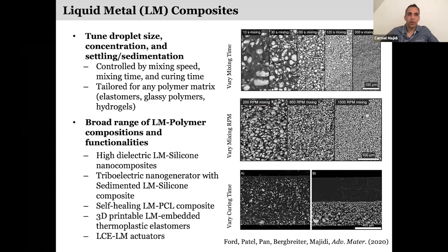Right, excellent point. So what we've observed and learned in our own studies is that these materials can withstand cycles. I mean, we've ourselves tested hundreds of thousands of loading cycles with the shape memory alloy. We haven't seen too much evidence of fatigue, and I am aware of studies that have looked at slightly different alloy compositions where you can achieve millions of loading cycles, so very high fatigue life with shape memory alloys. In the case of liquid crystal elastomers, I believe we've gone to close to 1 million loading cycles, and we haven't seen significant fatigue with those composites.